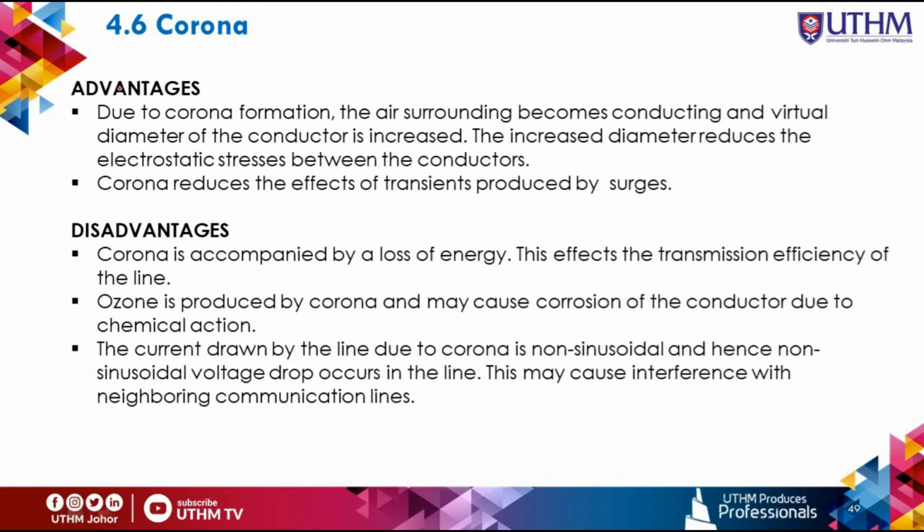Due to corona formation, the air surrounding becomes conducting and the virtual diameter of the conductor is increased. The increased diameter will reduce the electrostatic stress between the conductors. Corona also reduces the effects of transients produced by the surge.